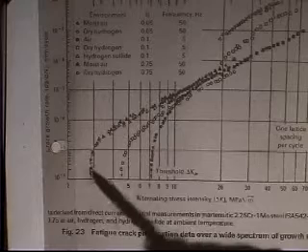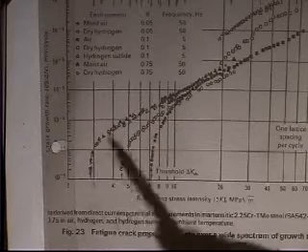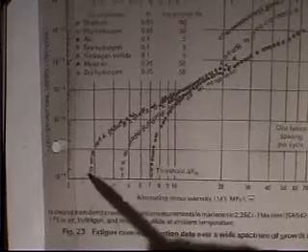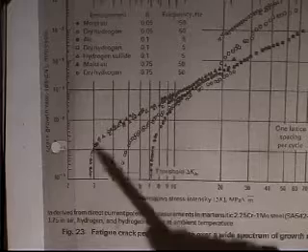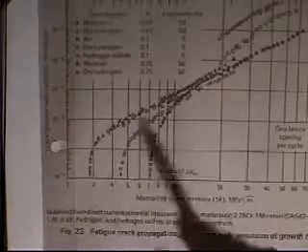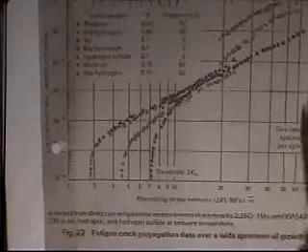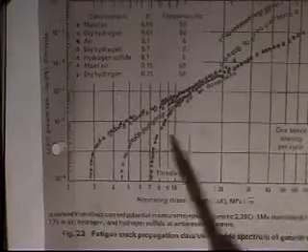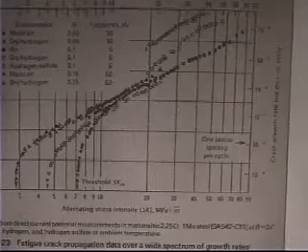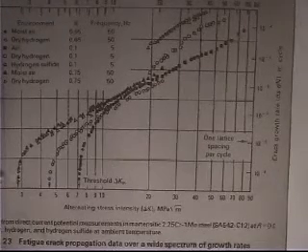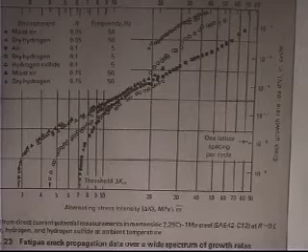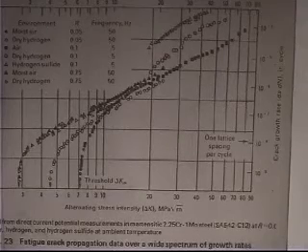Hydrogen actually causes hydrogen embrittlement. Hydrogen can start attacking the steel. And hydrogen sulfide does essentially the same thing. By the way, when you start plotting this, down here we're at 1 lattice spacing per cycle. So you're breaking 1 aluminum bond per cycle all the way across. You actually start measuring crack growth rates on these things that are less than an atom distance averaged across the whole width of the crack.